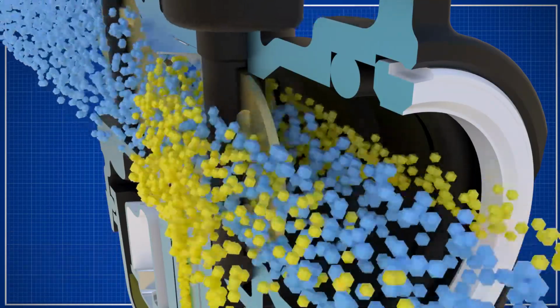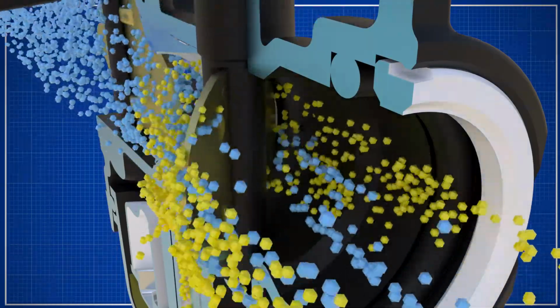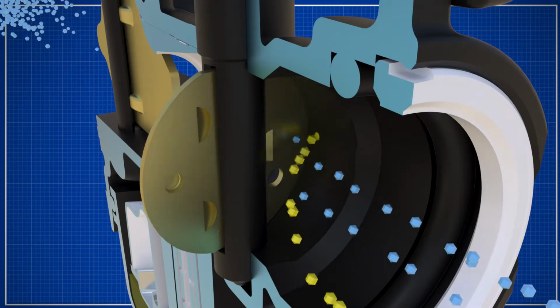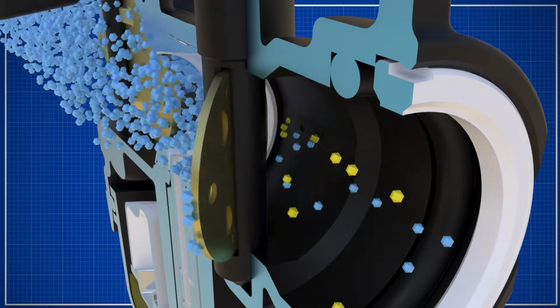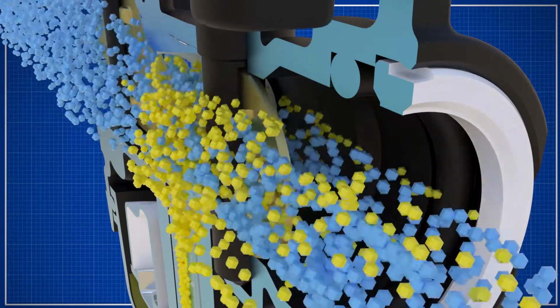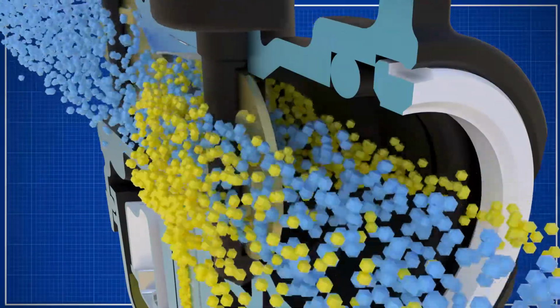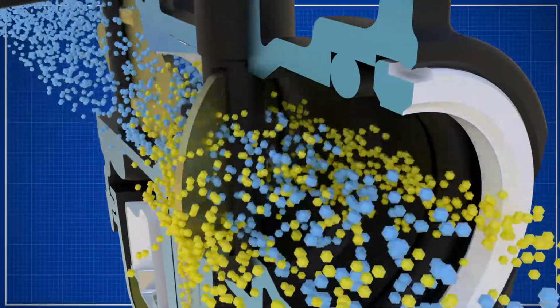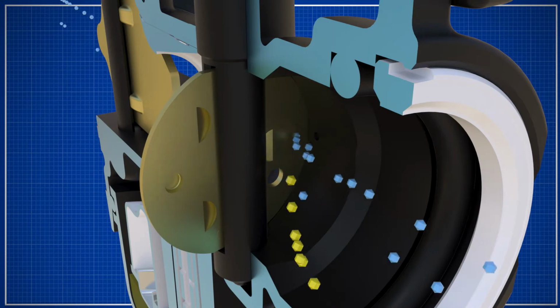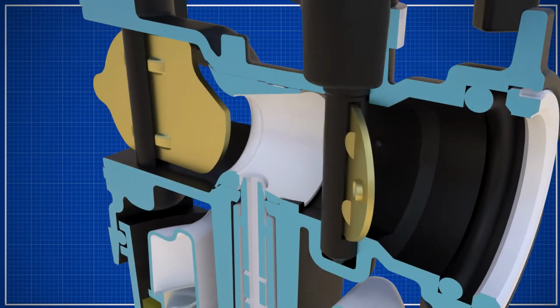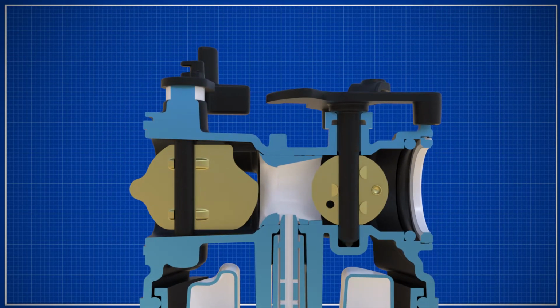The throttle plate physically limits how much air and fuel can go into the engine. More restriction results in lower engine speed. Less restriction lets engine speed increase. The other type of airflow control in some carburetors is a choke plate. This is not standard on all carburetors.